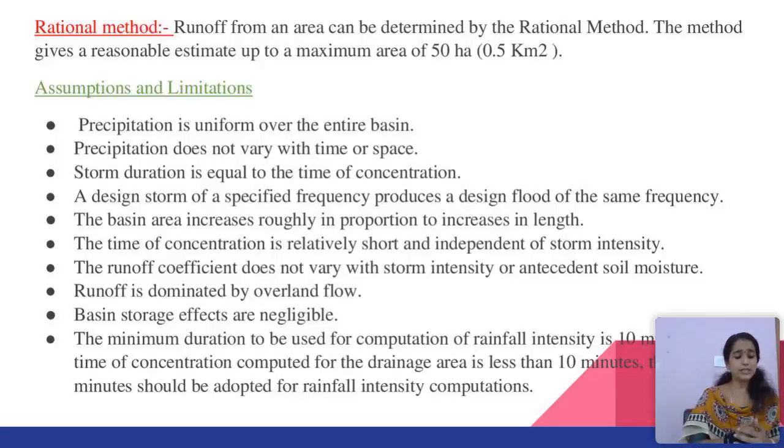Then the fourth assumption is that a design storm of a specified frequency produces a design flood of the same frequency. That is, we are considering a particular rainfall intensity as the design storm, and a design storm of a specified frequency produces a design flood of the same frequency. This is another assumption. The assumption has limitations also.